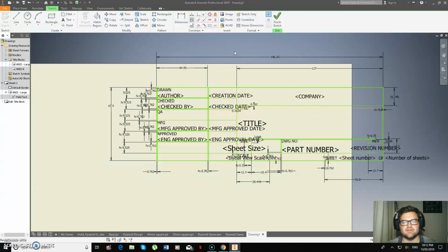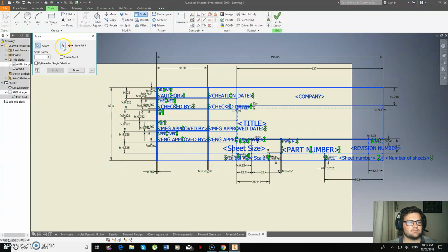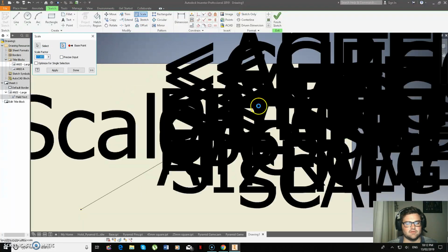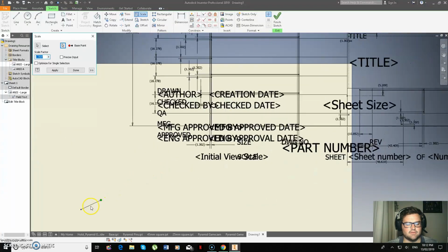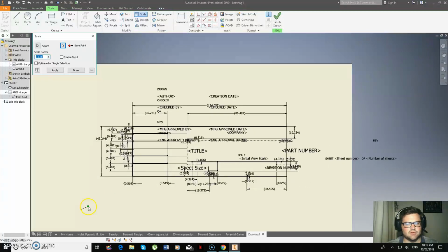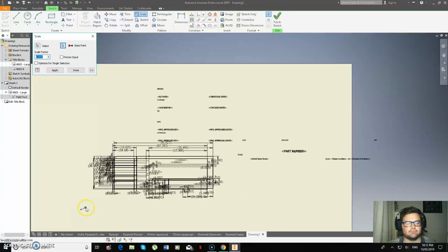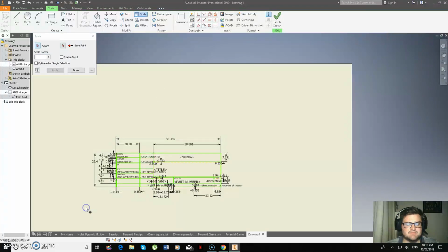Sorry, because I know lots of you guys follow this step by step, I'll give you an extra step there. So last thing I need to do is highlight this whole thing and then use the scale tool. And I'm going to use base point. I'm going to base point there. And then as I drag this further towards my base point, it makes it smaller and smaller. Now what I'm going to aim for is to stop when I get near 90 millimeters. And that actually makes it a really good size for the sheet.